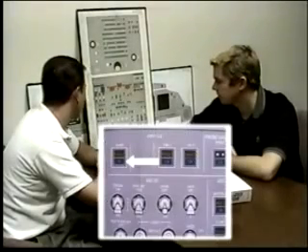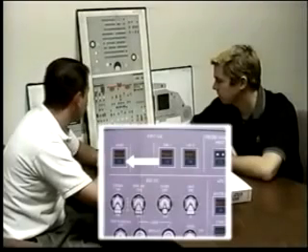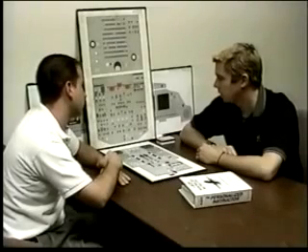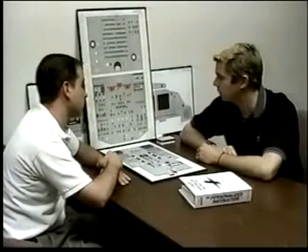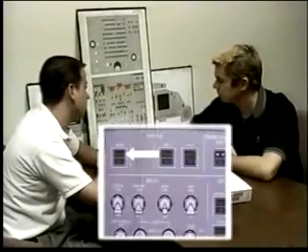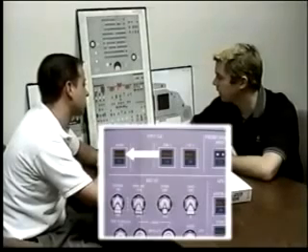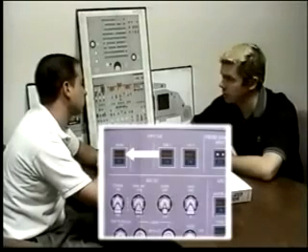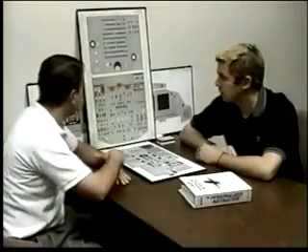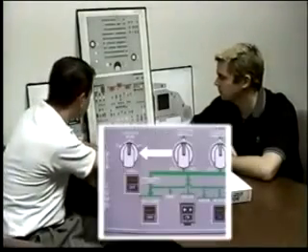Wing anti-ice. You select wing anti-ice to on. Where are you getting the heat for the leading edge, and what is it anti-icing? The bleed air manifold is supplying the air, and it's anti-icing the 3 outboard slats. Fault light in wing anti-ice? Indicates that there is a valve in transit, a valve disagreement, or a bleed leak. Good.